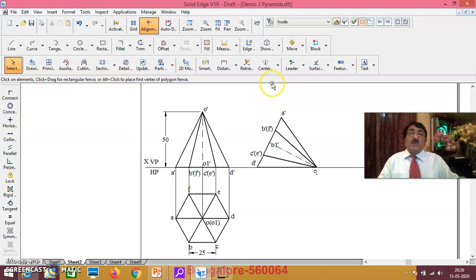Now as you look from here, the first step, as I said, is that the top view of this has to be written. When the top view has to be written, first step is get all the points and join the outer boundary of these points. Then step 2 is compare apex with the base. Since the base is nearer to the observer when you are looking from here, you have to darken the base. In the same way, as I told you earlier, you can do it. But first we'll get the points now.